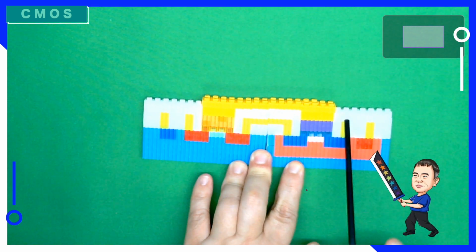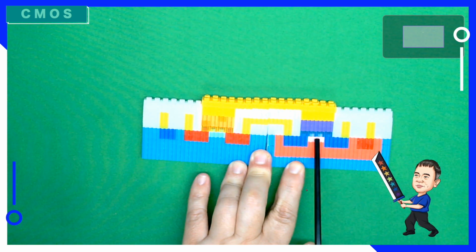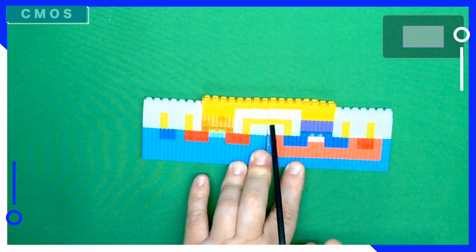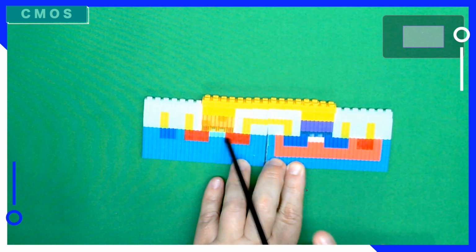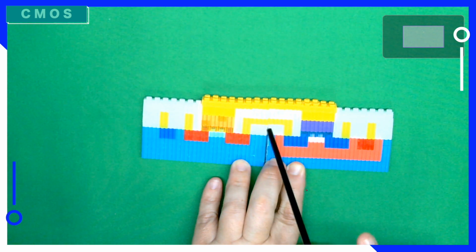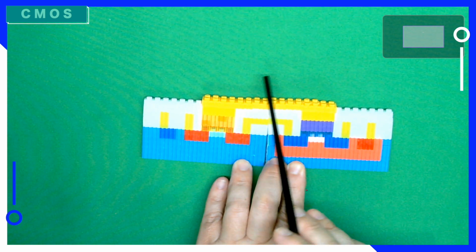So the current will come here through this light red, which is pink. The positive signal will come here and go to the output, which is in here. So complementary means, if I apply positive voltage, the signal will come from this side. If I apply negative voltage, the signal will come from this side to the output. Only one channel will be open at one time, and at least one channel will be open.